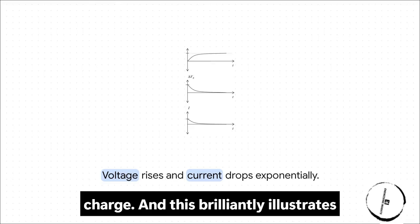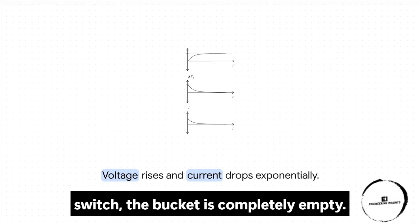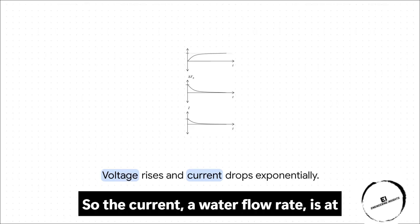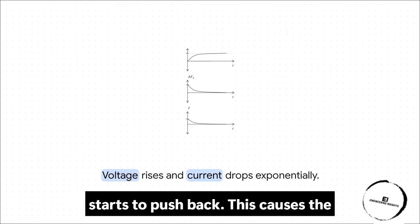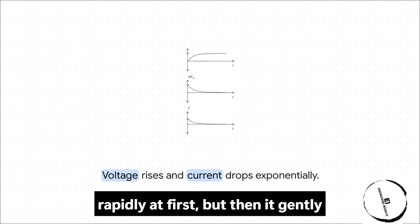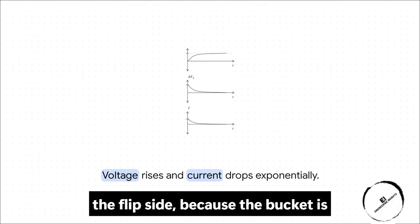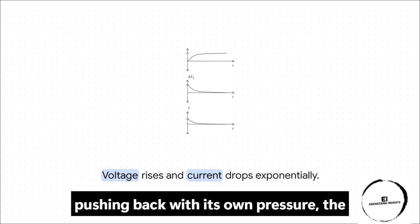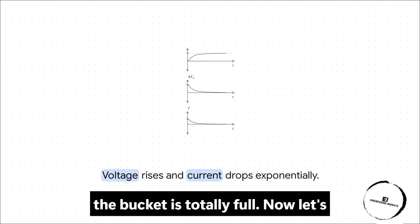And this brilliantly illustrates the dynamic reality of that whole filling process. When you first throw that switch, the bucket is completely empty. So the current, our water flow rate, is at its absolute maximum, just rushing in. But as the bucket fills, it actually starts to push back. This causes the voltage across the capacitor to shoot up rapidly at first, but then it gently levels off as it gets full. On the flip side, because the bucket is pushing back with its own pressure, the incoming current starts at its peak and just dies out exponentially to 0 once the bucket is totally full.